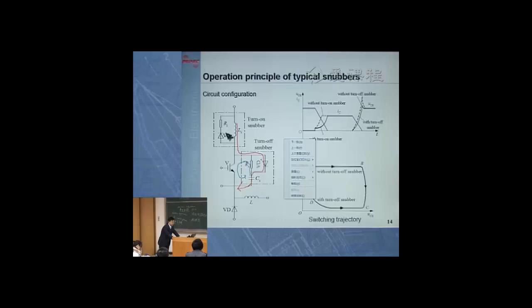Similarly, there's a turn-on snubber. Remember this parasitic inductance? When I turn on the IGBT, this inductance is actually good for us. Why?